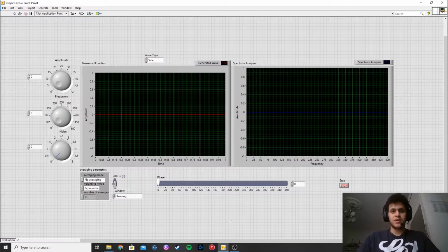Briefly speaking, the spectrum analyzer is a measurement device which displays a certain wave or a certain signal on the frequency domain rather than the time domain that we're always used to seeing. Therefore, at a certain frequency, which is the fundamental frequency, there displays a component, and if there are other harmonics, it is displayed in multiples of this frequency.